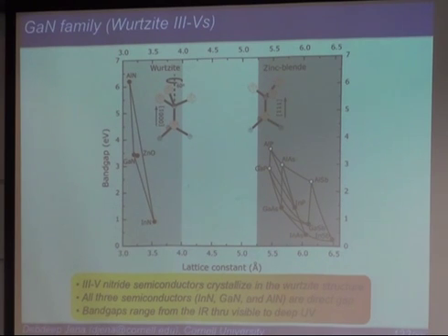And the reason for that is people grew the material. It's a very difficult material to grow. The crystal growth is difficult. But whenever they grew it and did an optical absorption band edge measurement, they always said it's 1.8 eV. Till 2000, when people first grew it by high-quality MBE, very good control, the growth technique improved quite a bit.